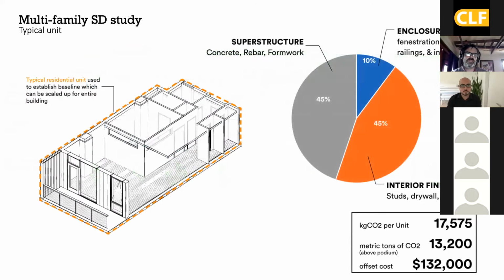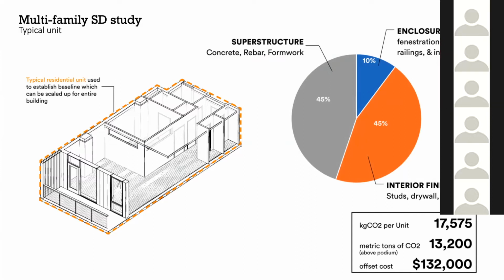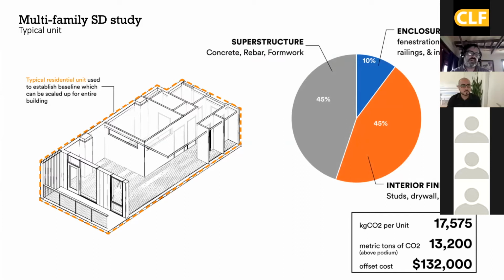If you go to the next slide, I just want to talk about a couple of examples of how we're using LCA. Whole building LCAs are great. They're aligned with a LEED credit, which can be really helpful. But we've also found that a lot of times we're doing those really late in the process. By the time the project has enough specificity, by the time the Revit model is built with accuracy, and with the time it takes to do an LCA study, it often happens a little later than we can influence product selection. Concrete is a notable exception because it really comes down to the mix, so that is something we can do a little later.